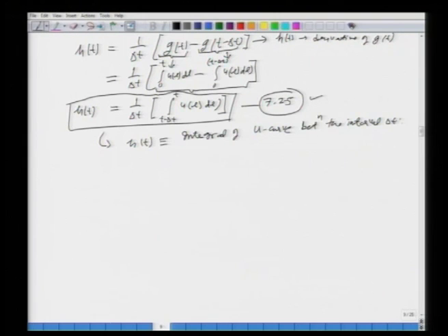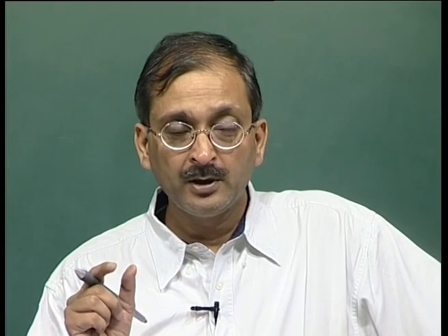So, you see that this h is nothing but your unit hydrograph. The way we have defined this h, or the unit pulse response function, it is due to the unit pulse, which is 1 centimeter of rainfall occurring in duration delta t. What is a unit hydrograph? 1 centimeter of rainfall occurring in duration d. So, it is a similar concept.